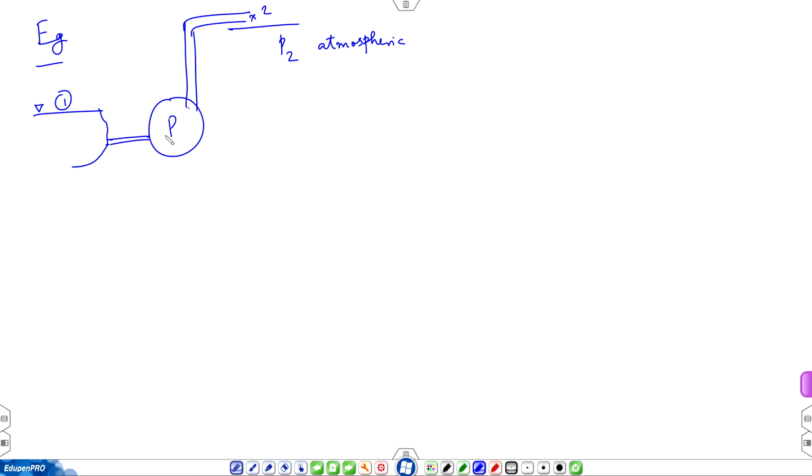So, what is the advantage of putting it at 1? You remember that in a reservoir, the level is not changing with time. So, velocities are 0. You know the elevation, you know the pressure. What is the pressure at the free surface? Atmospheric. So, it is an advantage in keeping point 1 over there. Now let us write the energy equation with losses specified as minus G H f. So, E 2 minus E 1 is equal to minus G H f minus W s.